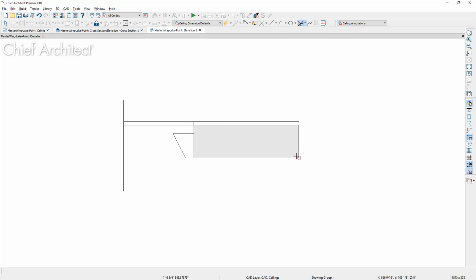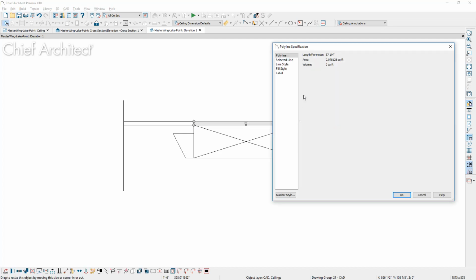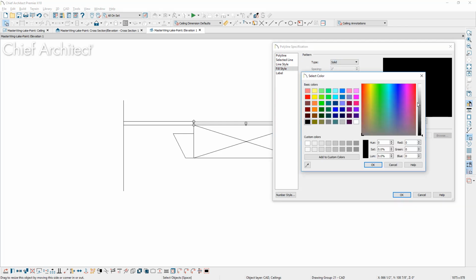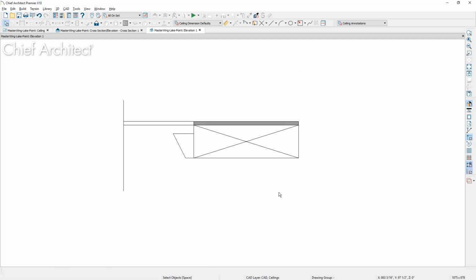the area for that soffit. And I'll just come in here and draw that in using a cross box. I might also just use a simple rectangular box to generate the ceiling platform. And what I did on my particular view is I put a small fill style in that area, and I just used a solid color and chose a simple gray that would then stand out as that platform finished ceiling that would come through, and then I can extend it over to where that break line would be.